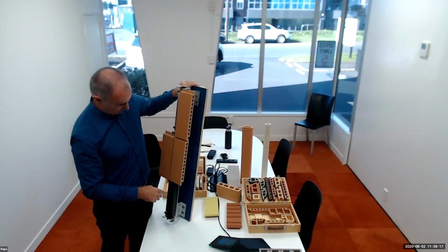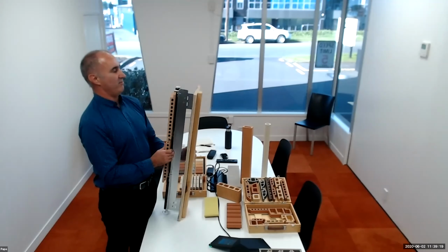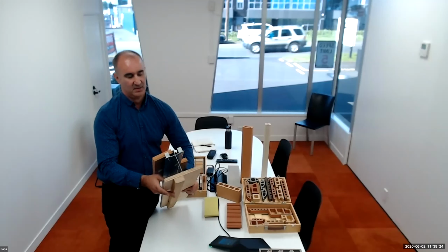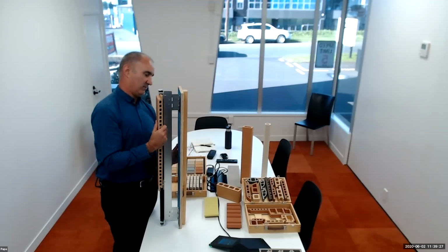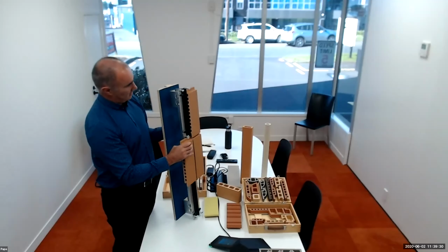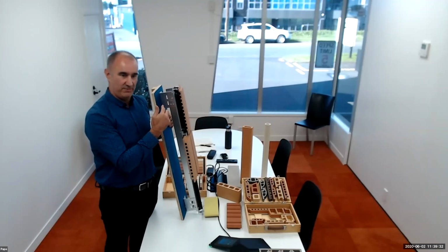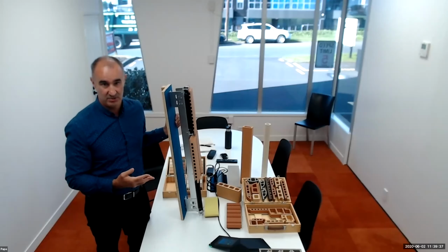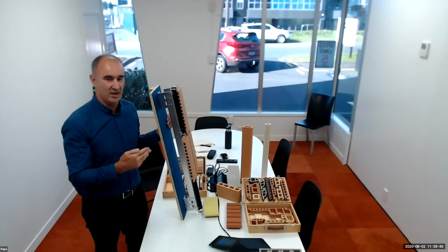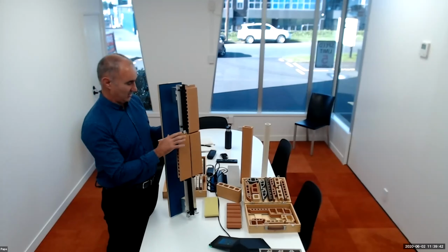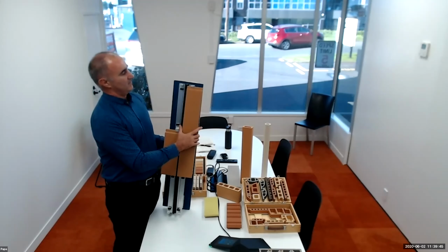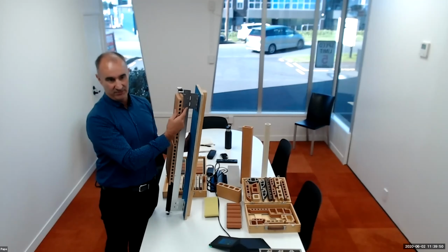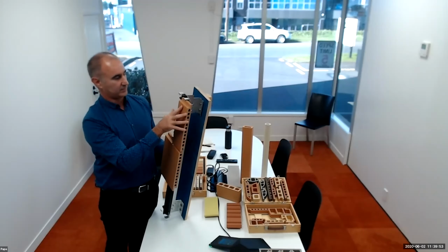For this particular method, there's a T profile that comes off the brackets that are back on there. That is fixed back using either what we call a floating bracket or a fixed bracket, dependent on your seismic requirements, seismic loads, that sort of thing. This is all engineered and designed for site-specific work, so we can help you take care of that. And then the tile itself is fastened back to that profile just using a clip system.